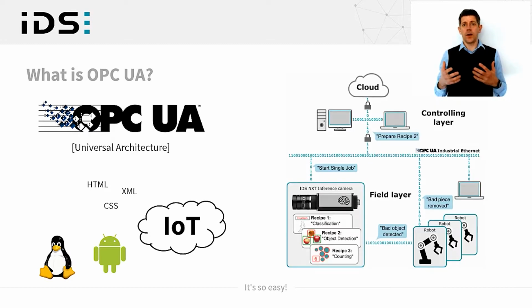Now, it's not enough to just have a new standard, and in fact you may even ask, is there the need for another control protocol? What makes OPC UA different is that it doesn't know or standardize device-specific settings and functions. OPC UA only regulates how devices communicate. And this means that the initial setup of a device is still done via a device-specific interface. But by using OPC UA, prepared tasks or recipes and prepared configurations can be executed easily.